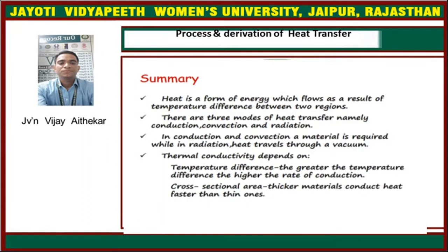Heat is a form of energy which flows due to a temperature difference between two regions. There are three modes of heat transfer, namely conduction, convection, and radiation. The greater the temperature difference, the higher the rate of conduction. As for cross-sectional area, thicker material conducts heat faster than thin ones.